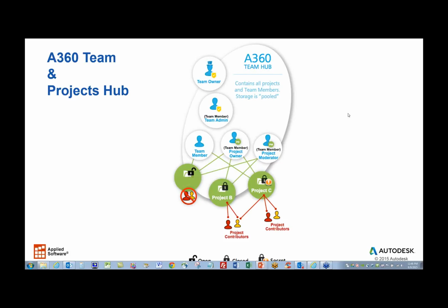Robbie, if you don't mind, do you mind describing the A360 team and project hubs? Yes, Rick, thank you. So when you set up your project for the first time on A360 team, which is a prerequisite, by the way, for collaboration for Revit, you're setting up that in a hub. And that hub has a team owner, and that person would assign an admin person who in turn assigns a moderator